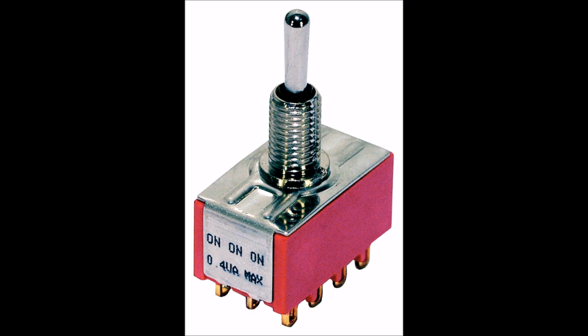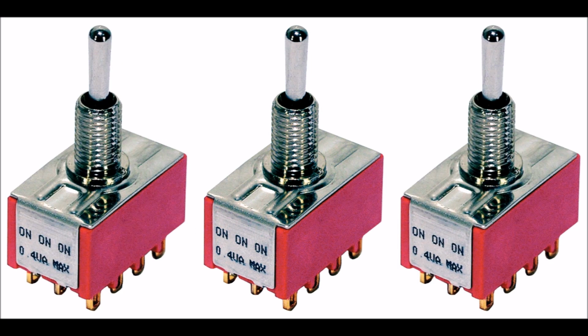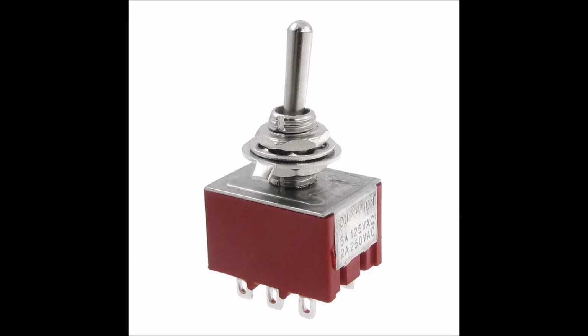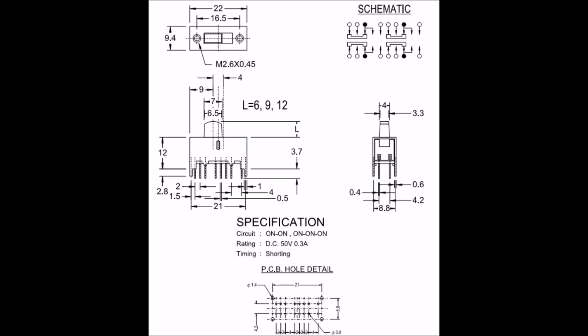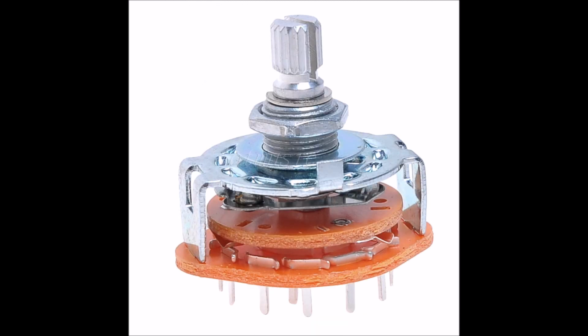As designed in the circuit diagram, this system requires 3 4PDT on-on-on toggle switches, which are quite difficult to find, usually available only online, and they are also quite expensive, and 1 4PDT toggle switch is usually more expensive than a respectable second-hand guitar. However, to bring down dream-level aspirations to tangible-level realities, for low-budget applications, properly wired 4P3T slide switches, or rotary switches, can be used, instead of the 4PDT on-on-on toggle switches.